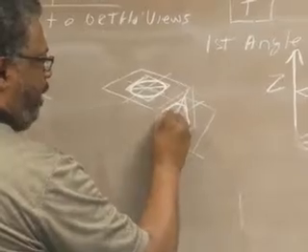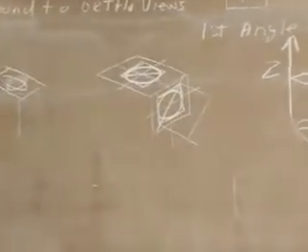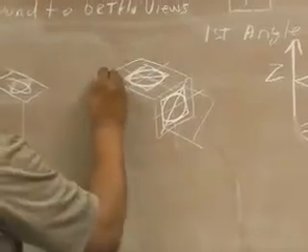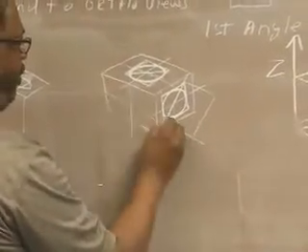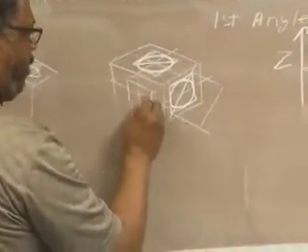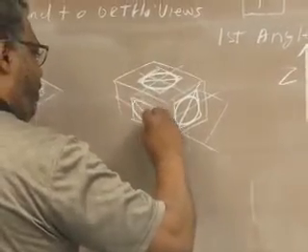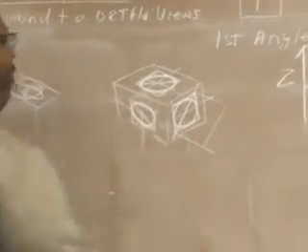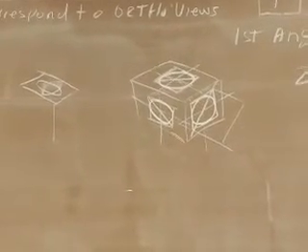My ellipse would be oriented like so. It's not round, it's elliptical. So if I come here, locate the center of my ellipse on this plane, create my box equal to the diameter of my circle, and establish the longest end of the ellipse, then my ellipse will be oriented that way. That's how you orient your ellipse.